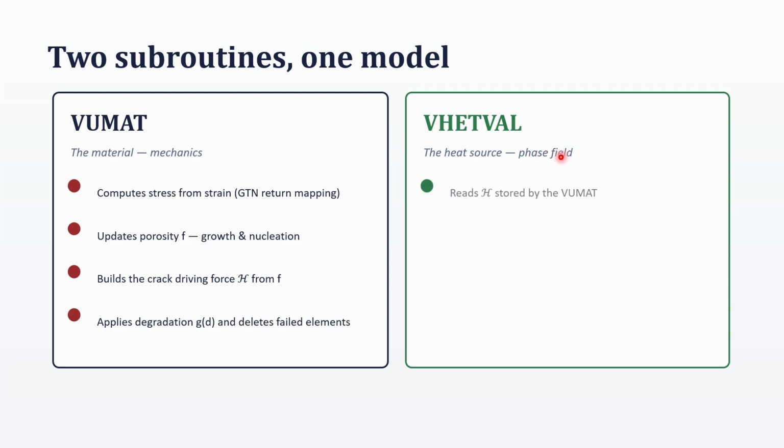Okay, so it reads H stored by the VUMAT. How? It reads H using the heat source term Q. It supplies the heat source Q to the thermal solver.